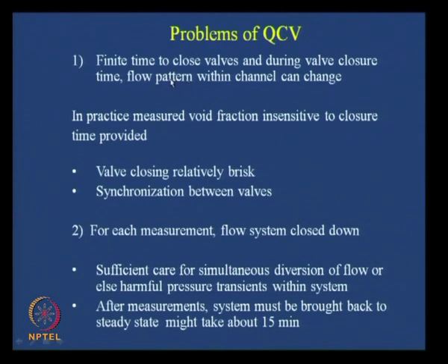So, in short, what are the problems of the quick closing valve technique? First thing is, it takes a finite time to close the valves, and during valve closure time the flow pattern might change within the channel. So, in practice it has been observed that void fraction is more or less insensitive to the closure time if the valve closing is relatively brisk and there is proper synchronization between the valves, so that both of them can be closed simultaneously. But the most important disadvantage I did not tell you.